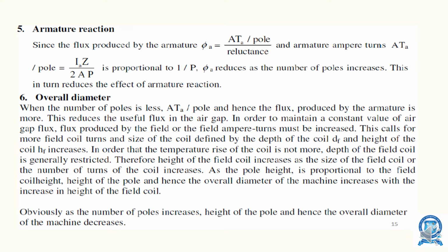This calls for more field coil turns, and the size of the coil, defined by the depth of coil df and height of coil hf, increases. In order that the temperature rise of the coil is not more, the depth of the field coil is generally restricted.